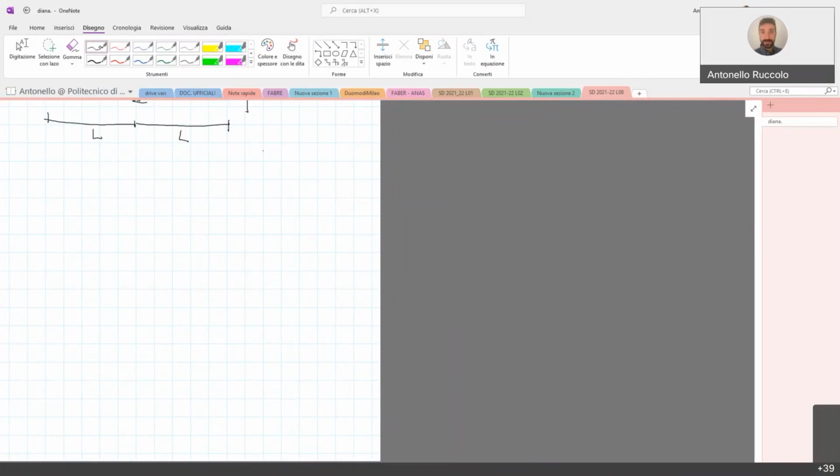Now we are providing the nodes with more restraints in order to study the effects of any class of displacements, namely vertical displacement, horizontal displacement, and rotations. We study the effect of each unknown displacement in the nodes that we have. In our case, it is node B.